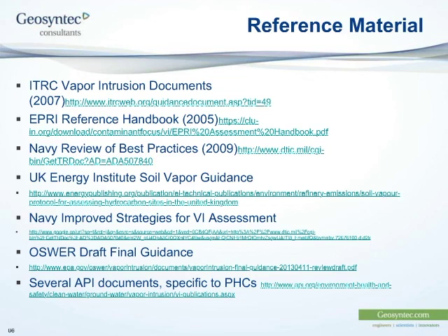Now, one of the most interesting and inexpensive ways to assess the potential presence is through measuring the pressure in a soil gas probe over time. If there is a barrier in the vadose zone, a deep soil gas probe will not always have the same pressure as the atmosphere. So if you hook up a pressure transducer, you'll see a signal that goes all over the place, that's not just a zero gauge difference.